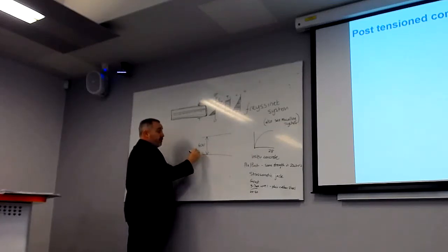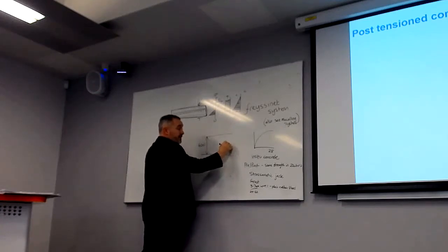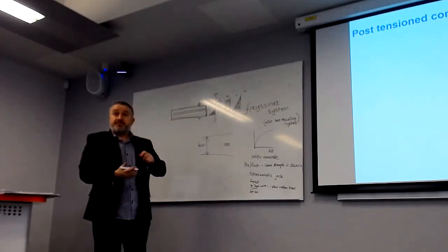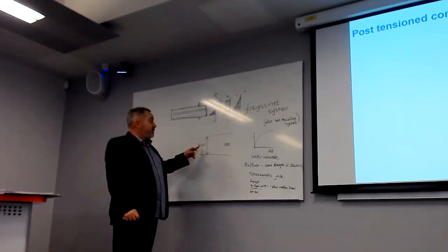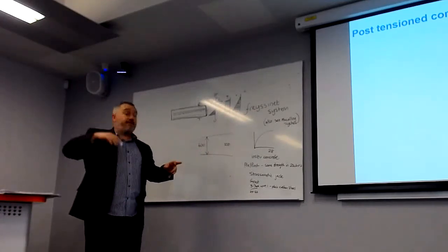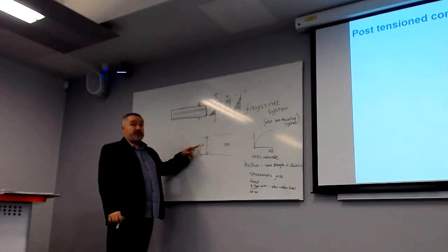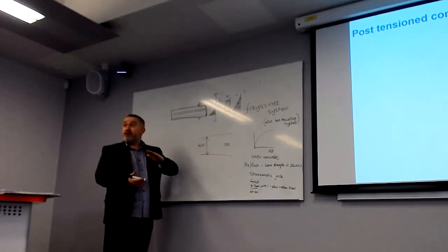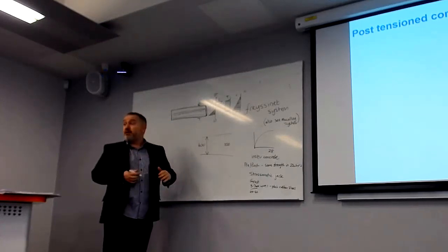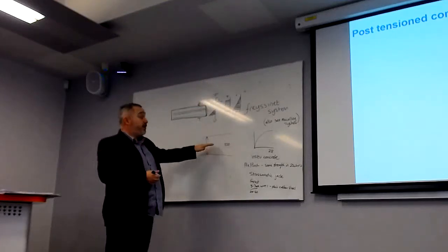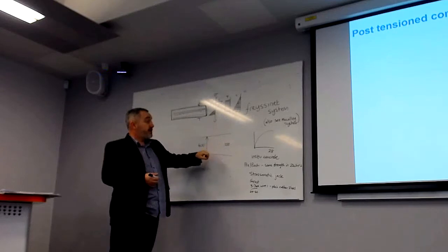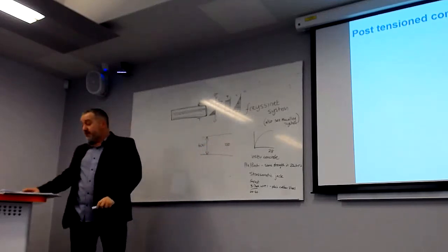Tensioned floors can go all the way down to 100 thickness, and so the big difference for this is that, over 10 floors, you're gaining sort of 300 mil every floor. And if you've got a restriction on the height of the building, then you're going to get more floors in if you use these tension floors.